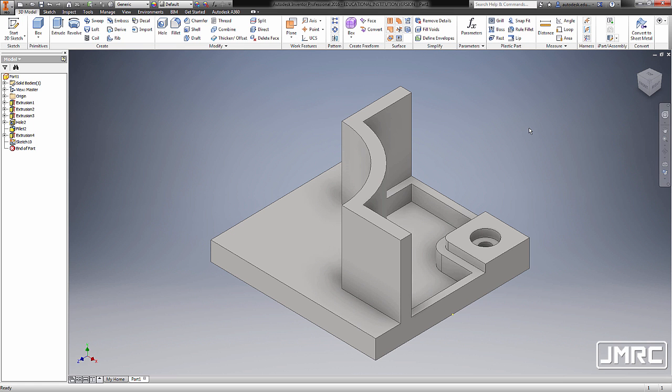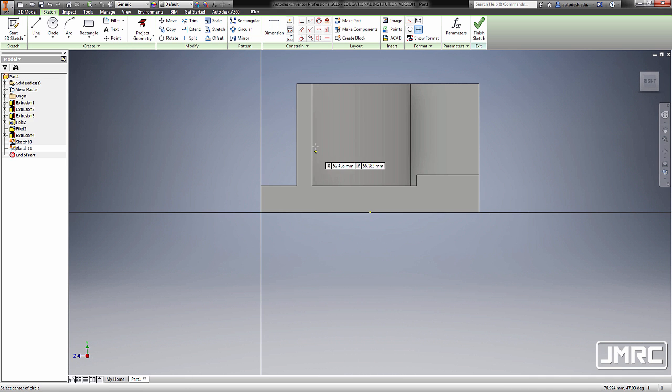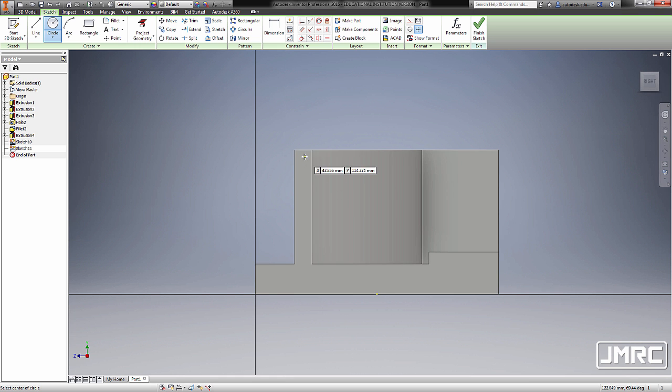Now I'm going to hit Control Shift C for a circle and I'm prompted to select a plane or face, selecting this face. I'm going to pan, zoom in. I'm going to drop our first point here. Now the diameter of this circle is A divided by 3. So 225 divided by 3. Pressing enter. I'm going to grab our coincident constraint, select our center point and our midpoint.